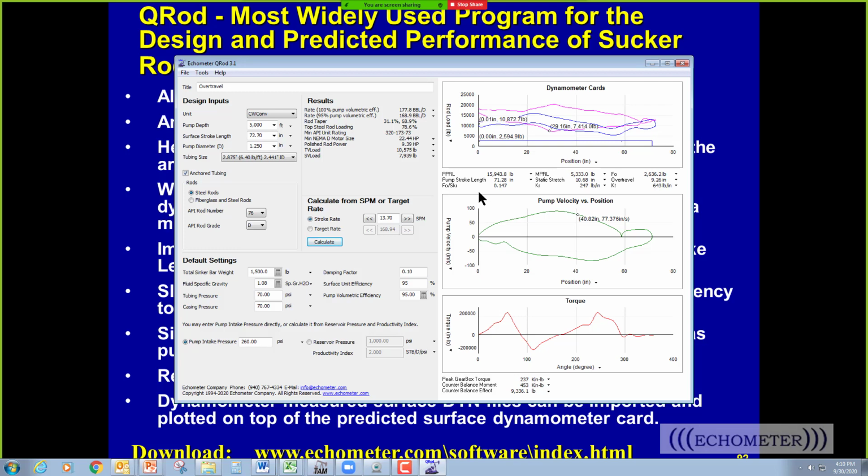You have to change the stroke length so it's short. You have to change the plunger size so it's small in diameter. Or since you're on gas and you don't care about your gas bill, you can run a variable slippage pump from Harbison-Fischer that leaks, and you can fill your pump up on the downstroke with slippage. At the top of the stroke the pump will be full, because if you space out the variable slippage pump at the top of the stroke, the tubing fluid will fill back up the pump and it'll be full every stroke.